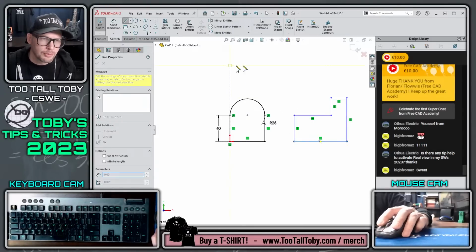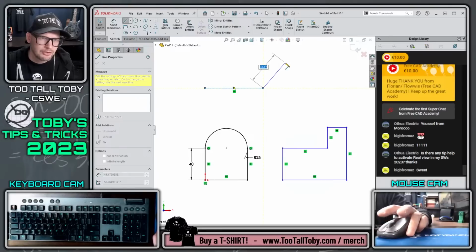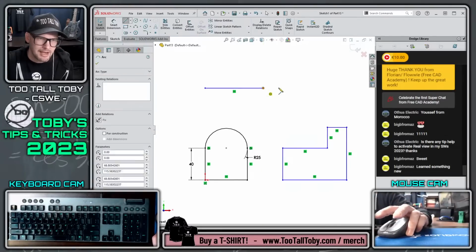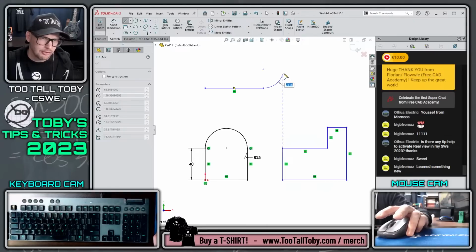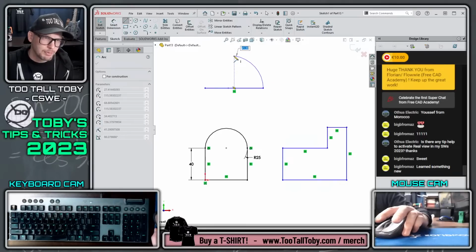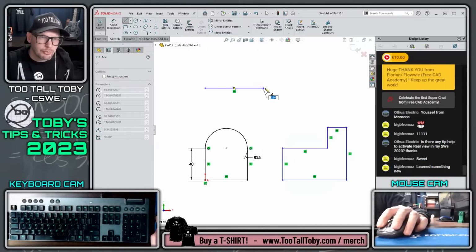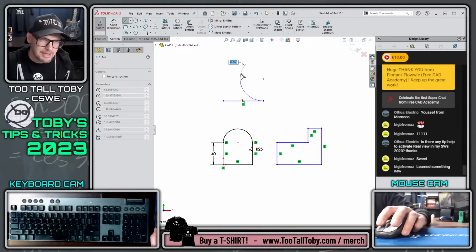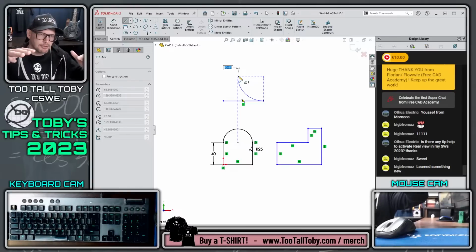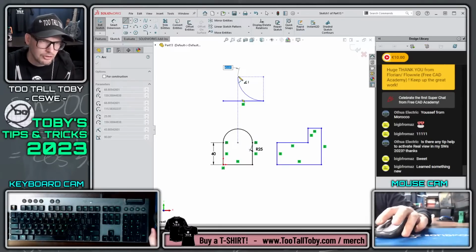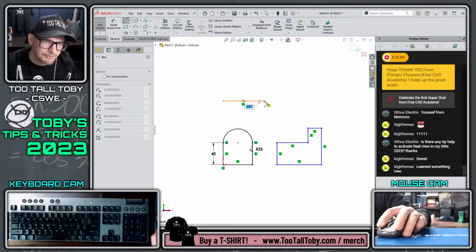It's also worth noting since we're talking about this, when you do that tangent arc function, I'm not clicking anything, I just come back, hold my mouse over the endpoint, you can come off with an arc in 8 different directions. So normal tangency, positive, negative, or up or down, perpendicular tangency, which is super useful, like if you're going to revolve a spherical revolve, this is how you get into it really quickly, and also reverse tangency. So when I'm manually filleting a shape that's got weird curvature and I need to manually sketch a fillet to cut extrude, this is what I would use for that. So you can actually go in 8 different directions, and the way that this works is you just hold your mouse over that point, and then whichever direction you begin moving your mouse in, that's the direction that the tangency is going to be assigned to.